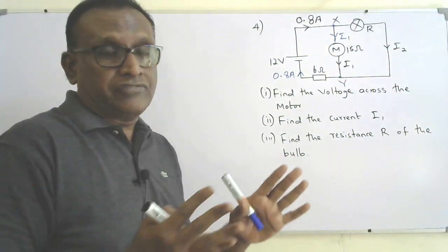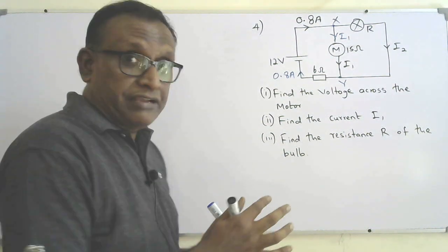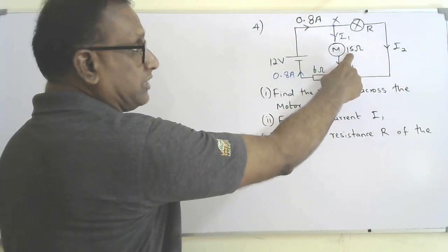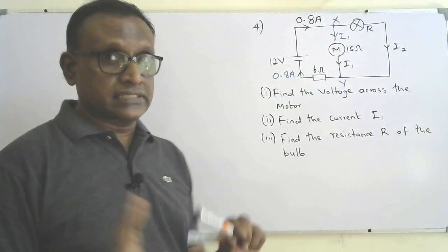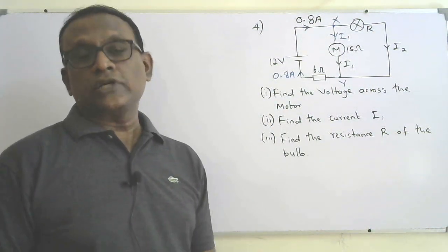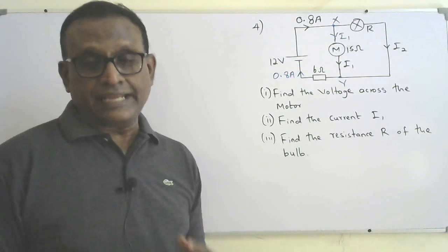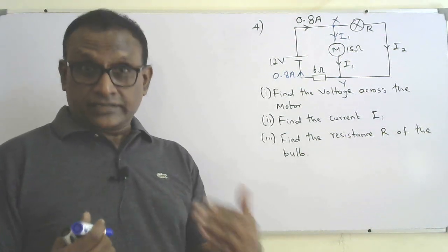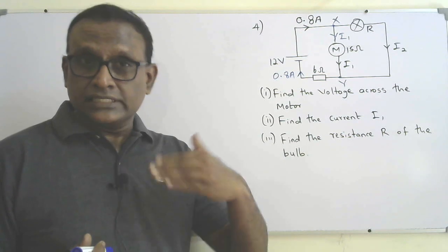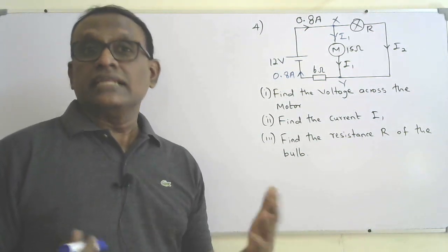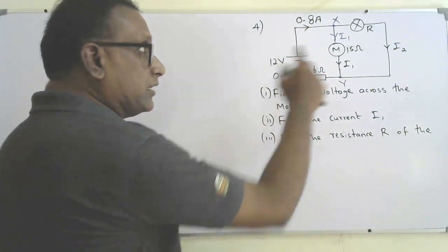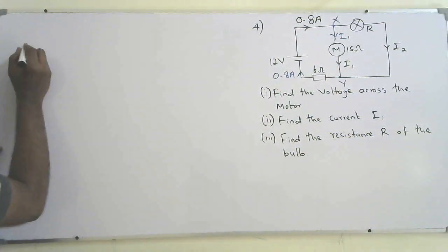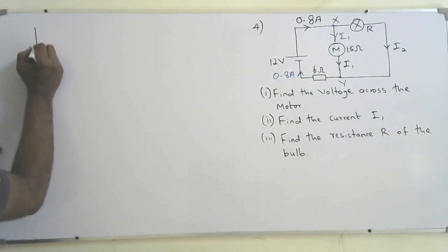So if I find the equivalent resistance of 15 ohms and R, it must be connected across the junction. That's a rule, is it? When components are connected in parallel, and if you find the equivalent resistance, that equivalent resistance must be connected across the junction. Please go through the lesson 4, the fourth lesson. There, I explained everything already. So I can redraw this circuit again like this.